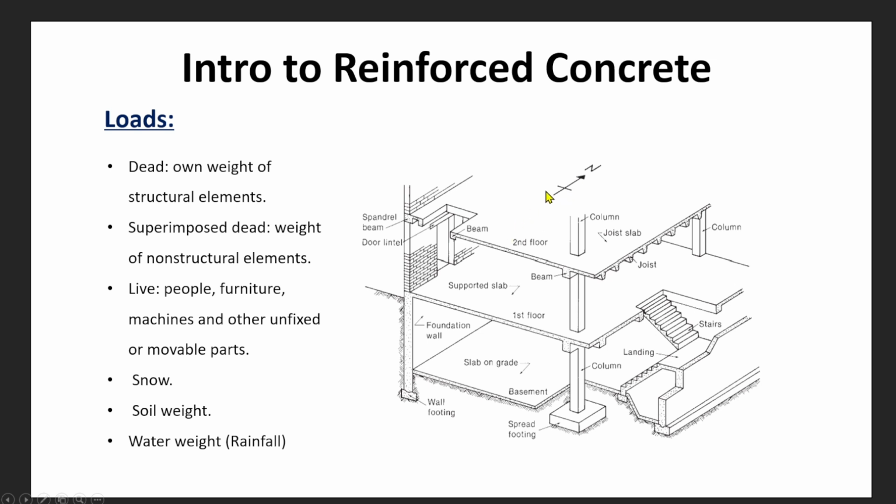So we have here the loads, and they are just distributed in this slab, and then it will be moved to the beams. We have joists and beams there. The joists distribute and transport the load from the slab to the columns. The columns are transferring the loads to the foundation, and the foundation is transferring the loads to the soil.